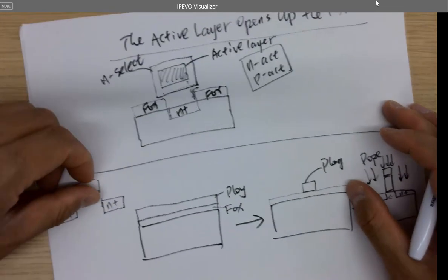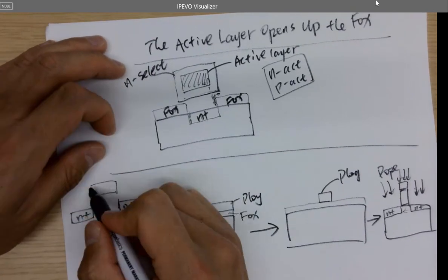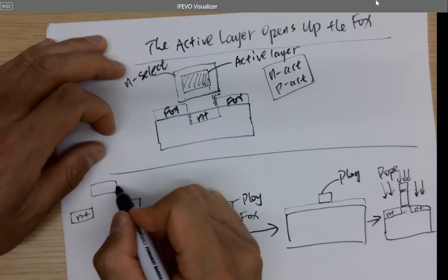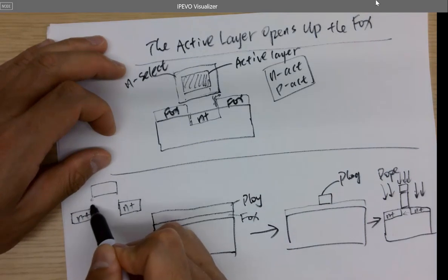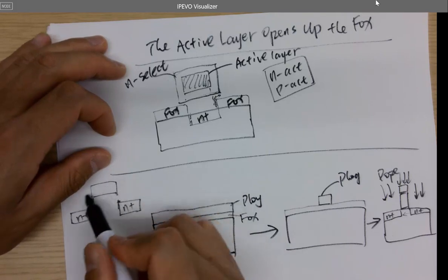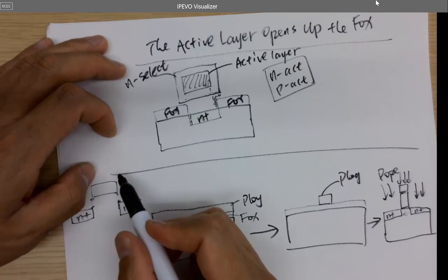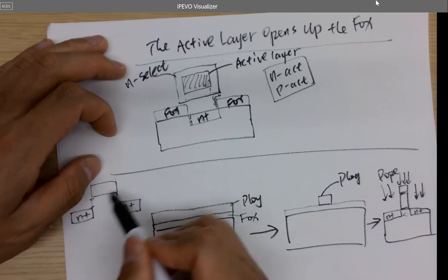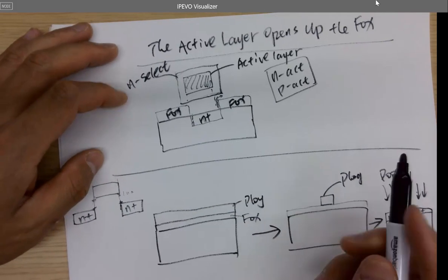Okay, if you dope the diffusions to the wafer first, and then you want to put the polysilicon on the top as a gate, again, these are nanometer dimensions. How can I make sure you can put the polysilicon square directly on the top of the channel? Just perfectly aligned without even 1 nanometer change. It's very difficult to align it.